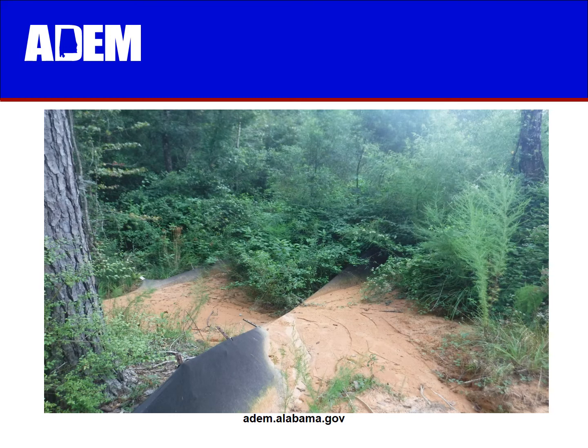Another problem related to silt fences is improper maintenance. Large accumulations of soil against a silt fence can lead to soil overtopping the silt fence, which allows soil and turbid water to run over the top of the silt fence, rendering it ineffective. The proper installation and maintenance of silt fences is critical for staying in compliance.